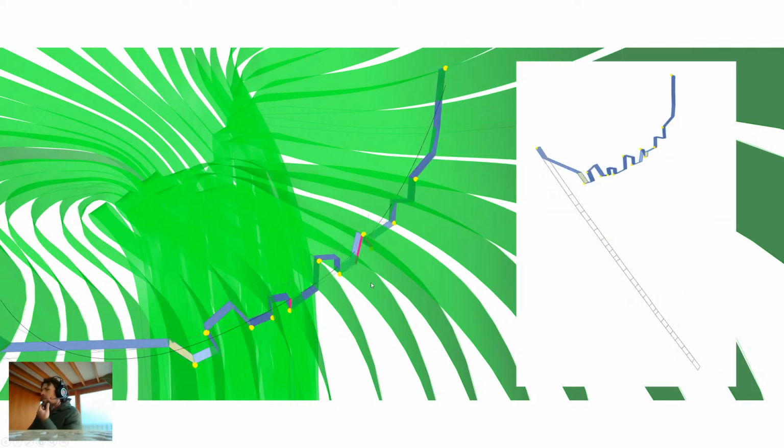And so we ended up using a physical simulation in Grasshopper, just using Kangaroo in fact, that we're happy to show you guys if you're interested, in order to simulate all these fabrication constraints. So to make sure that the bend angles were always within what we knew we could bend, as well as maybe 10 other fabrication constraints like that, and to make sure that our steel part would unroll into a straight strip so that we could just use stock lengths of stainless steel to manufacture all of these brackets. And this again just saved an enormous amount of time and money because we didn't have to laser cut or CNC cut anything for the project. So all of these steel parts are just made out of lengths of stainless steel, even though they're all three-dimensional and entirely unique.